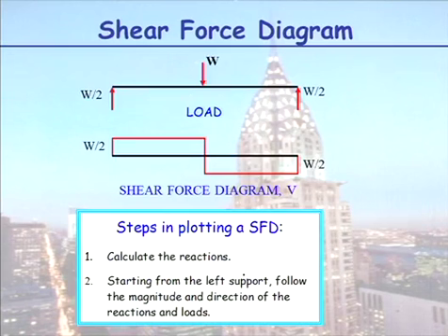Easy peasy, how to plot a shear force diagram. Start at the left-hand end and follow the loads. You can't get easier than that. In saying that, calculate the right reactions, please. Okay? If you have time in the exam, and I know it is stressful, calculate reactions twice. So in this problem here, it's symmetrical, but I would take moments at A, solve for them, and then very quickly take a moment at B and check I get the same reaction. So you're 100% you got it right. That's if you're unsure, if you know you're prone to making errors. If you don't make errors, don't worry about it.